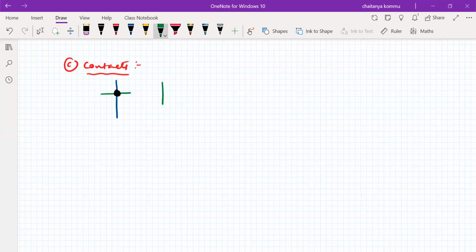For example, an N diffusion crossing another N diffusion. There is no need of contact. Okay. So both are equivalent to each other. That means without contact, the same materials will be connected together. Something like this also, for example, diffusion and diffusion. Contact is not required, but they are connected.